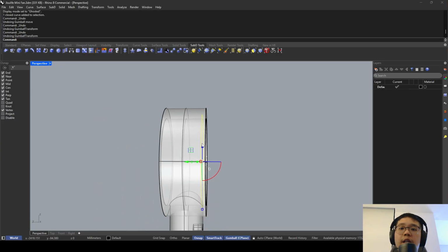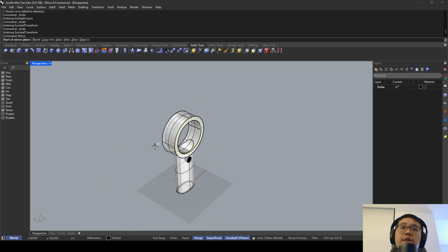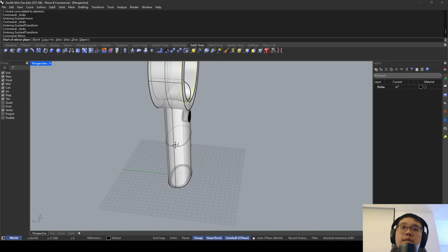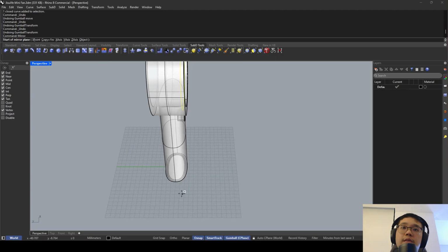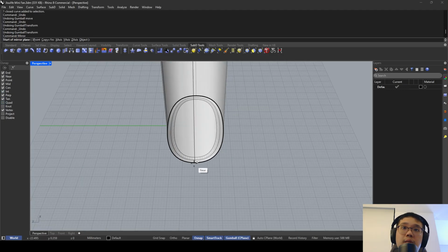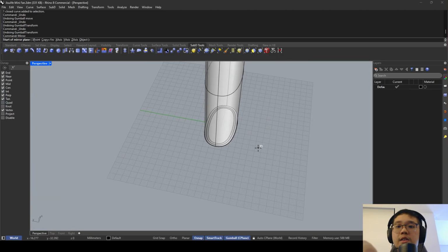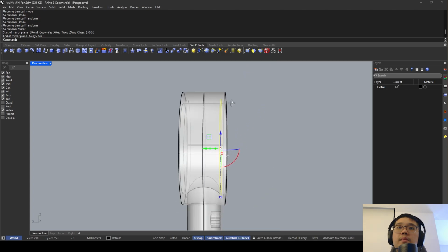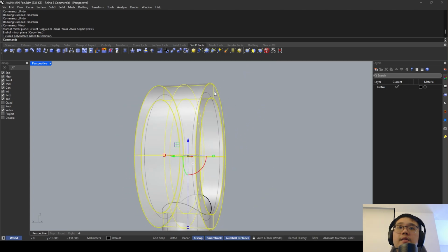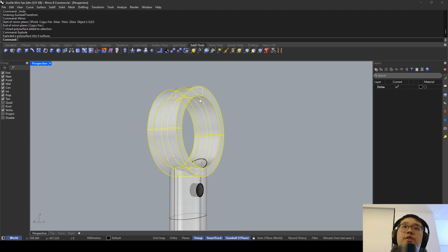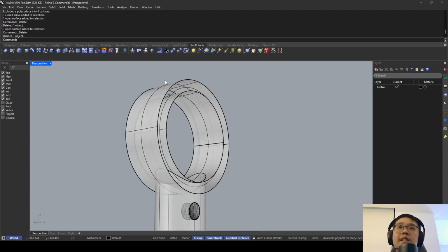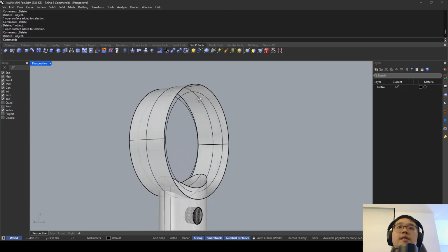Comes in 3 mil, and then I will just mirror this again so it goes on the other side. If I can find the midpoint. It's okay, I can just command 0, 0, 0. Make sure it goes to the center. And I will just explode this actually. It's gonna get quite complicated, so I'll just explode, delete this.